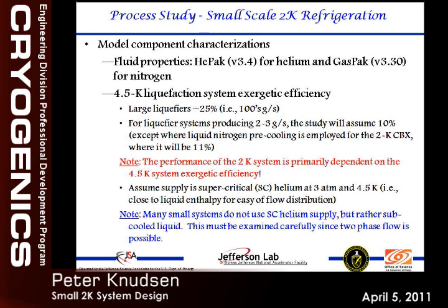It's also worth mentioning that the exergetic efficiency of that 4K plant is a very strong variable in regards to the overall efficiency of the 2K system. So the better that efficiency, the better your 2K efficiency. Also, we'll assume that the supply pressure is supercritical, and mention that a lot of smaller systems don't use supercritical supply.